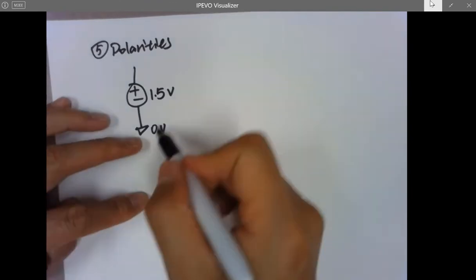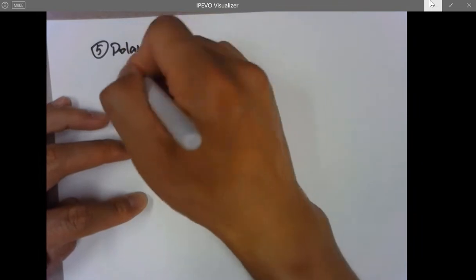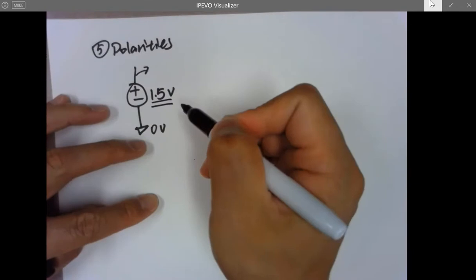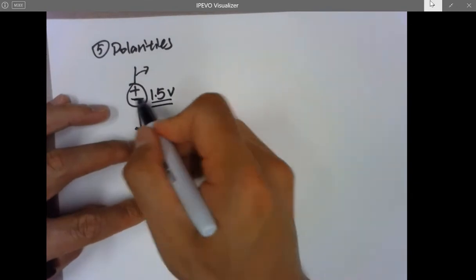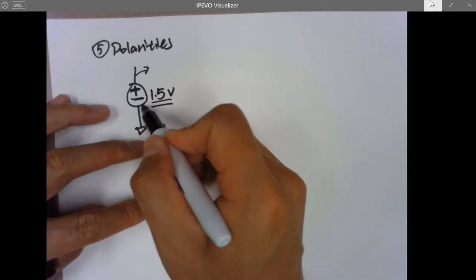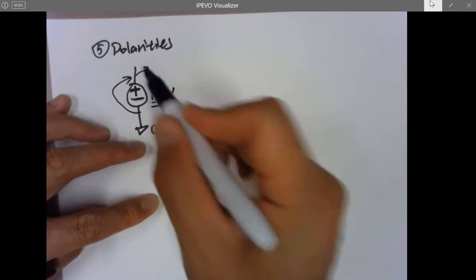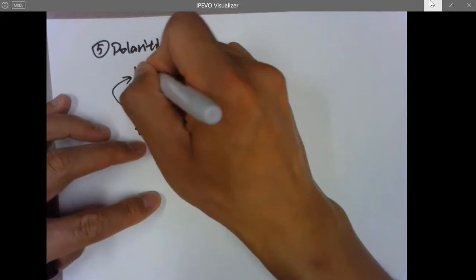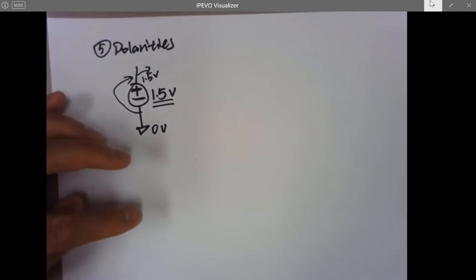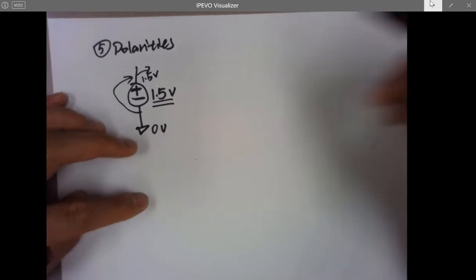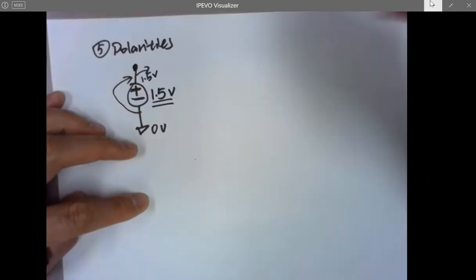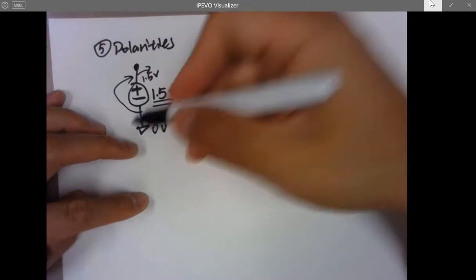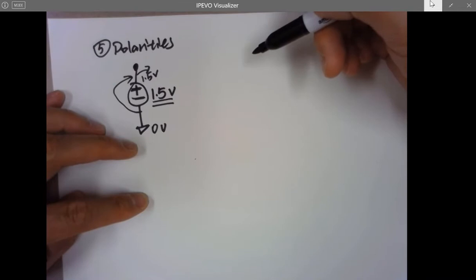All the voltages are built up based on this common ground voltage reference. Okay, so if I label here as a ground, what's the voltage here? Think about it. Because this is a 1.5 volts battery, it's going to force the voltage from here to here as a 1.5 volts boost, which means the voltage here will be 1.5 volts. And I didn't say compared to where, right?